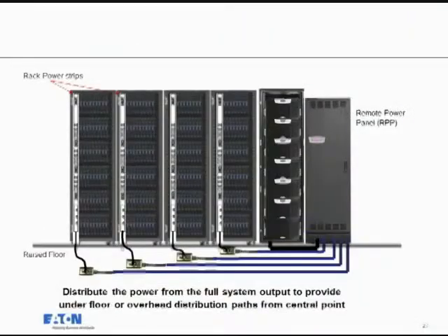In this example, I'm using a 12 kilowatt block, and I'm putting 6 of these UPSs together to get a 60 kilowatt N+1 system in this particular design. Same as the other blocks, same as the other drawings, but here, in this particular case, it's a 12 kilowatt 3-phase block capable and scalable to 60 kilowatts.